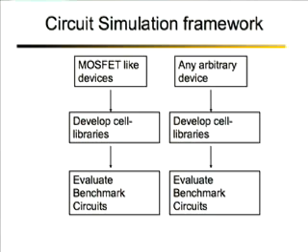And our idea is to get this new device and try and figure out what would be a system and circuit level performance for this device. So we can similarly develop the cell libraries for this device, characterize the cell libraries for delay and power and leakage, and then evaluate some benchmark circuits. So these are two different ways in which the tool can at this moment evaluate any new device technology.